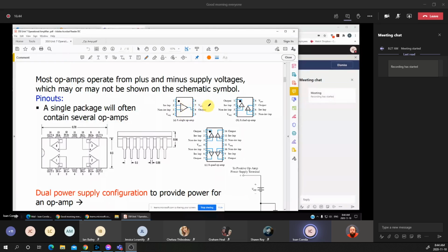Now, on the small size, the mini dual inline, we may see a single integrated circuit. We may see a V plus, like positive voltage. I mentioned that the notation for the negative and the positive voltages is not standardized. We may see the dot, which is always placed on pin 1, and going clockwise.